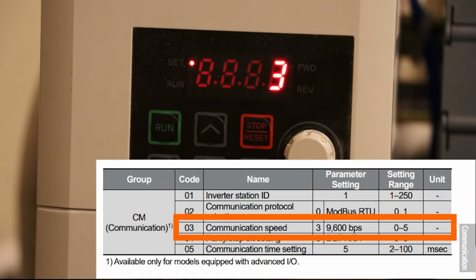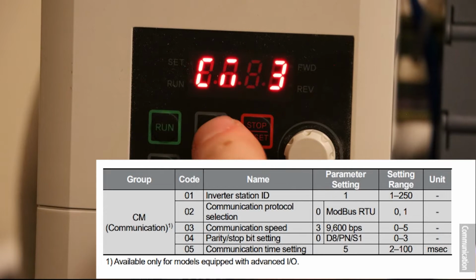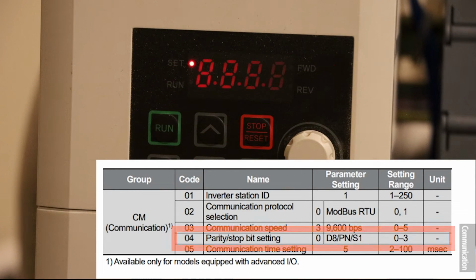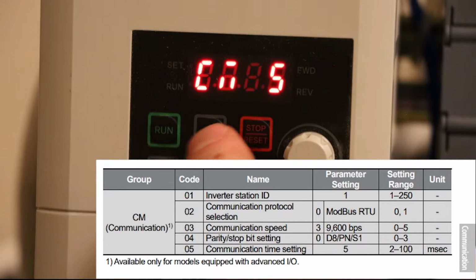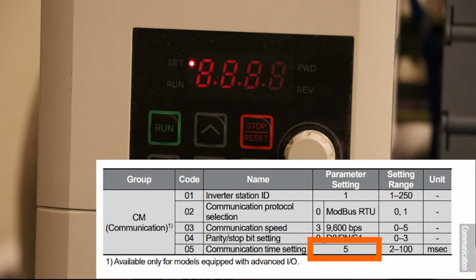CM3 should be 3, yeah, for 9600 baud rate. CM4 should be set as 0 for having 8 data bits, no parity, and 1 stop bit. So yeah, this is all just the normal industrial standards. And CM5 is 5, which is a 5 millisecond timeout. So that's all of our settings done nice and easily.